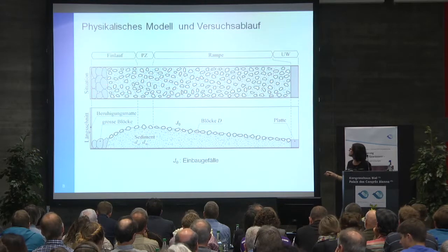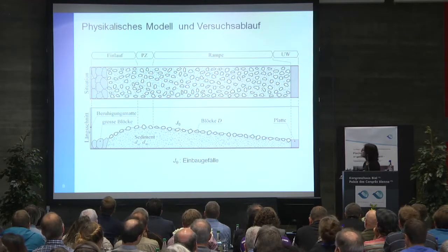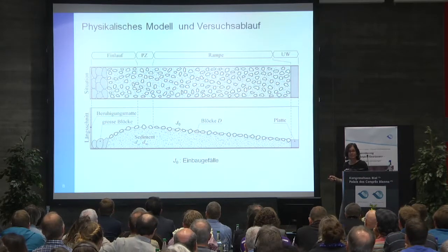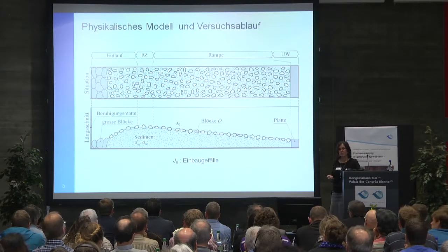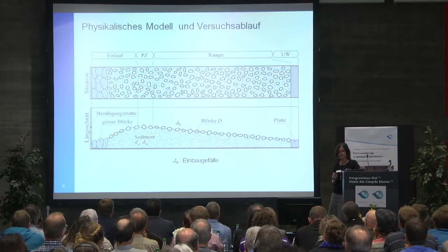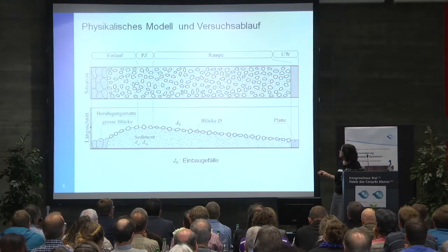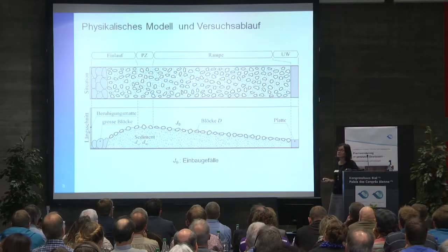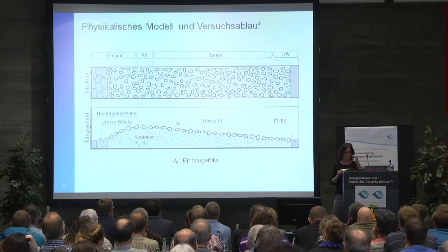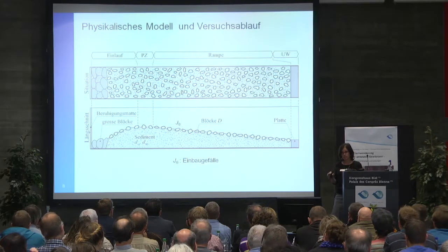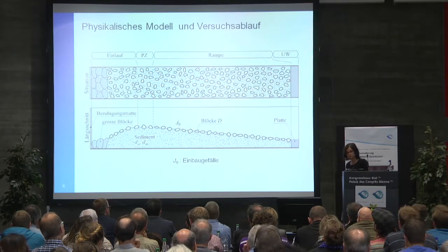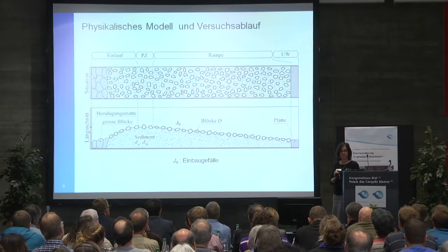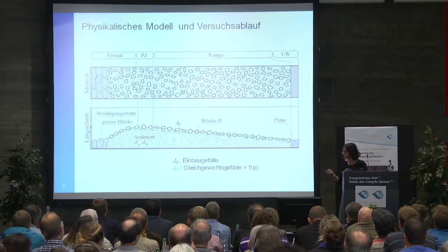You see how we built the ramp at the beginning, also in a cross-section, which is not that important. The inlet, the buffer section, was necessary due to the channel. The slope was 5%. That's relatively steep for such a rock ramp with a specific sediment material and the size of the rocks. Then we charged the system with the same flow until balanced conditions were achieved, which meant that nothing is moving anymore and the ramp is stable.